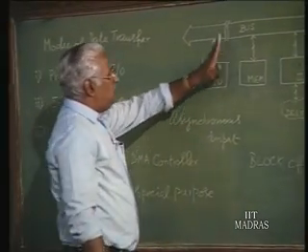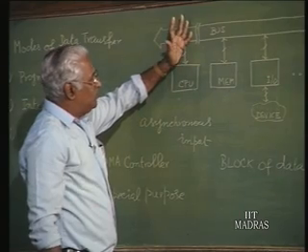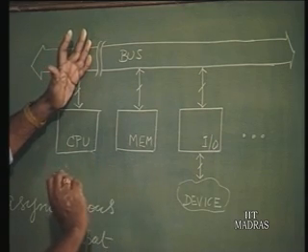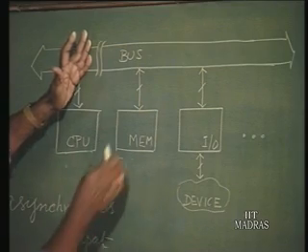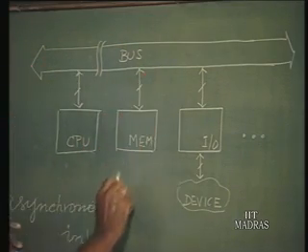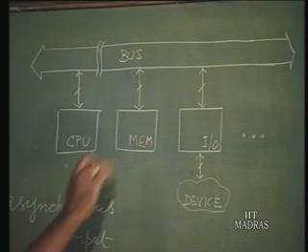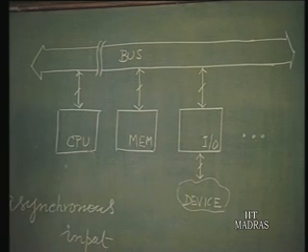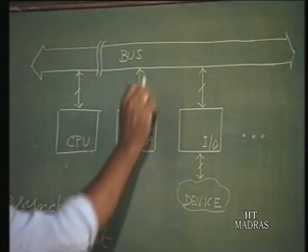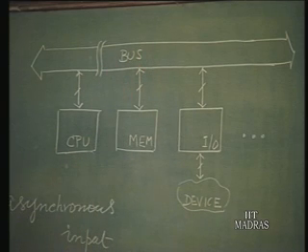So, what we say is the CPU is cut off from the bus and a DMA controller will take over, right, and that particular one is going to sit on this bus necessarily. The DMA controller, now you can see I have to introduce the controller here. What is the best way? Suppose I can make use of the same set of signal lines that are there in the bus.